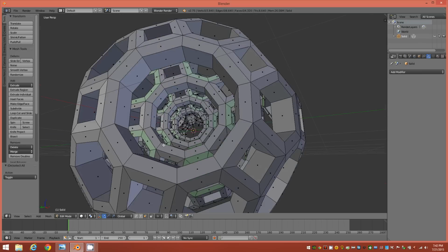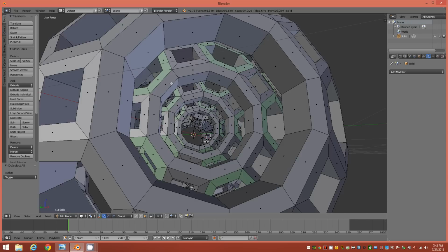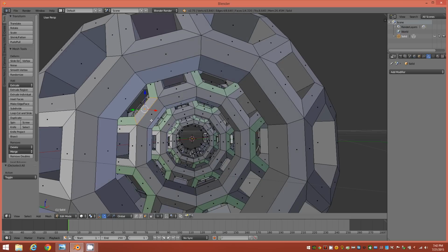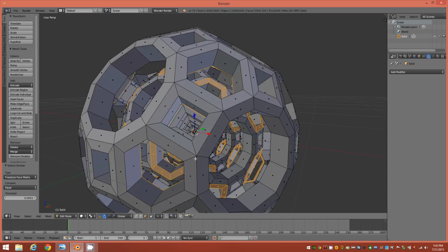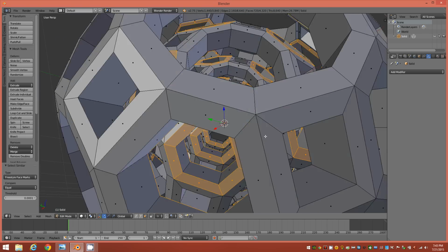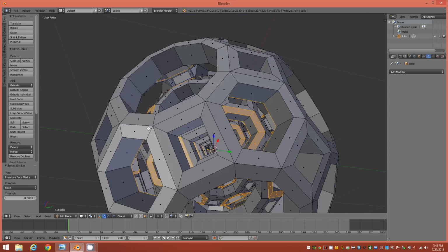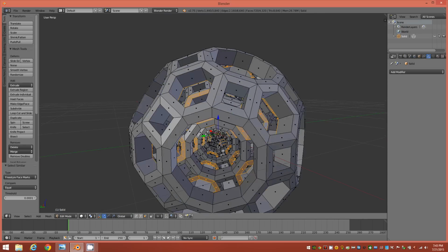These selections are preserved, and if we want to bring them back later in our workflow, we just select one of the marked faces, bring up Select Similar by holding down Shift and tapping G, and choose Freestyle Face Marks, and that will bring back the selections that you've marked. So that's one way to preserve selection sets in Blender. Now that we have all of these faces selected, we can go on to the next step of the process.